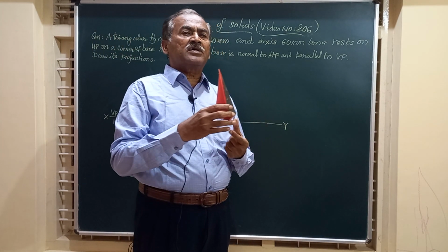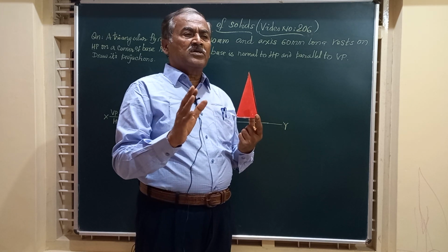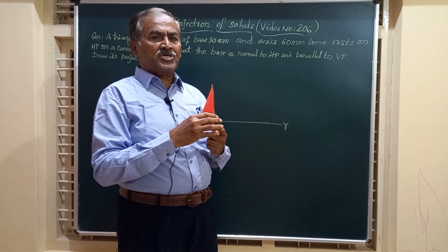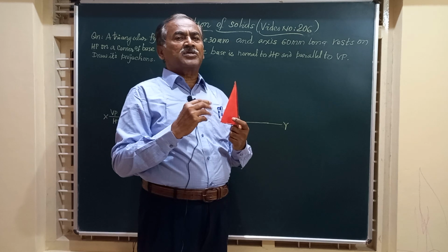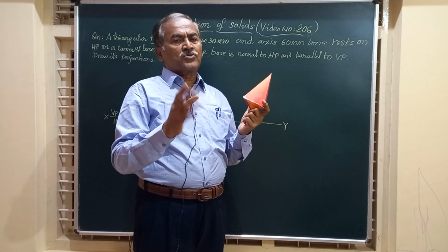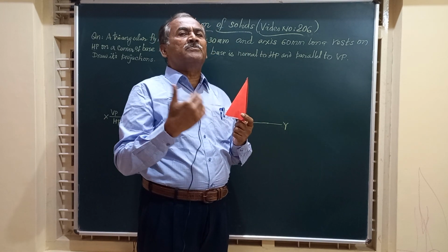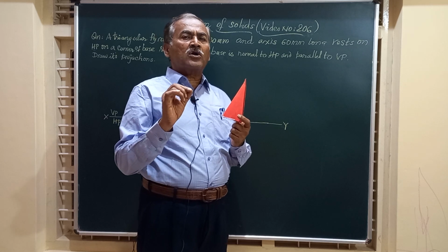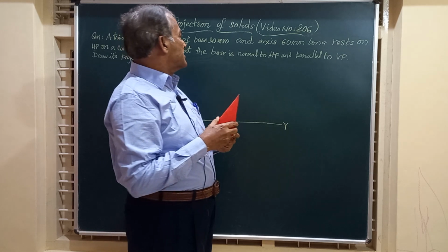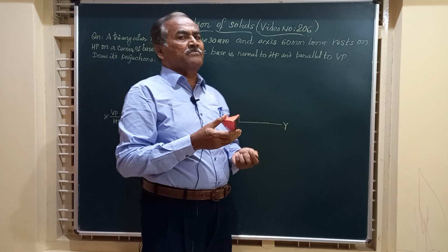Friends, initial placement of the object is very important. Generally, in all problems on the solids projection, there will be three positions: the initial position, the first tilt, and the second tilt. If you go wrong in the first step, all the other solutions will be wrong, and the students will not be awarded any marks for that. Hence, friends, let us see how the object is on HP on a corner of the base.